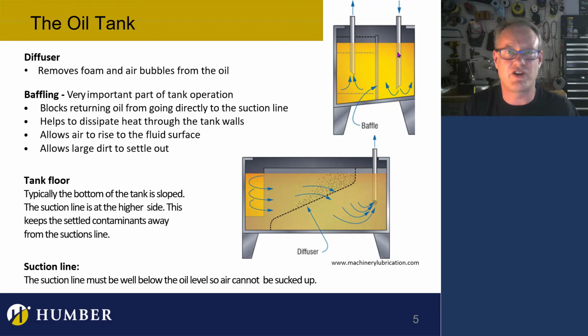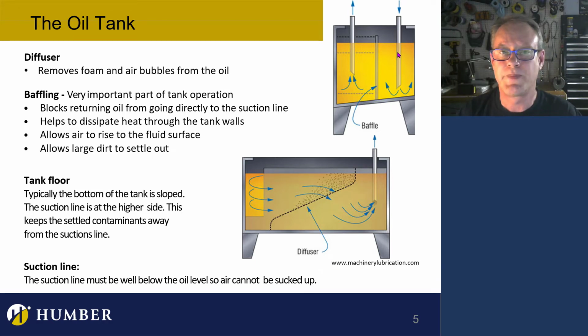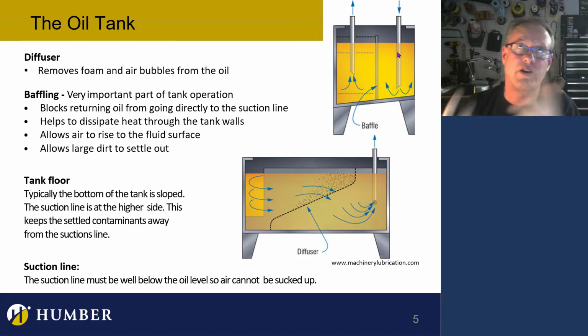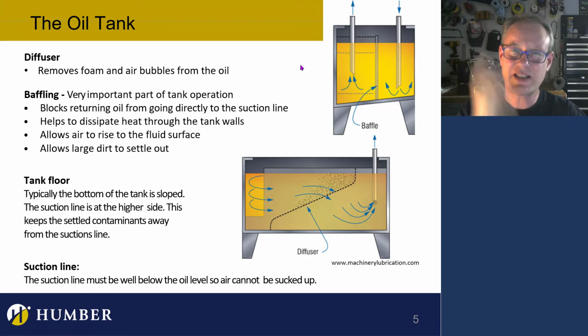If there's air in the drain line, if that line doesn't go below the fluid level, then there's going to be air in it, and that air is going to get sucked up, or it's going to get into the system somehow. So we've got to make sure that our return line is below the fluid. Pardon me, I said drain line, which is actually something else.